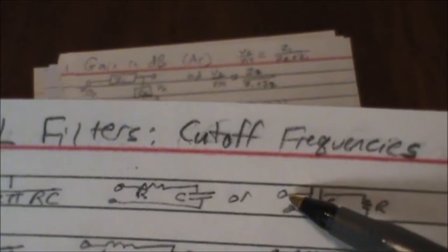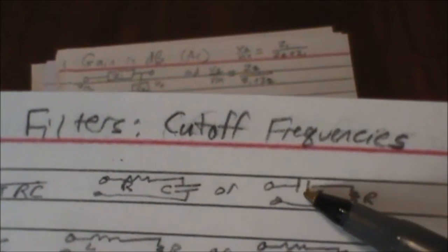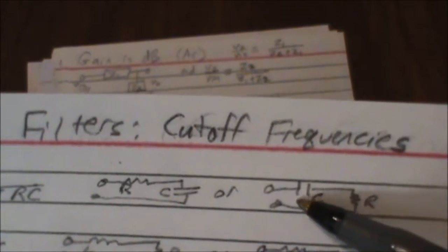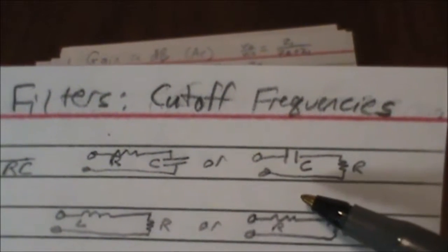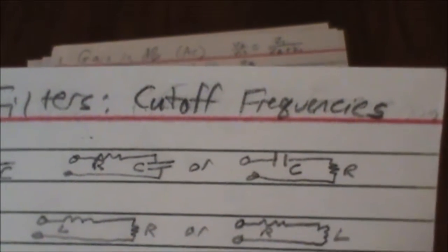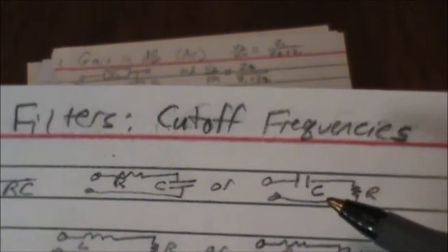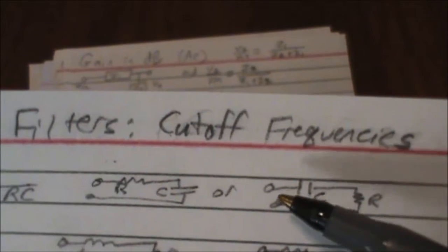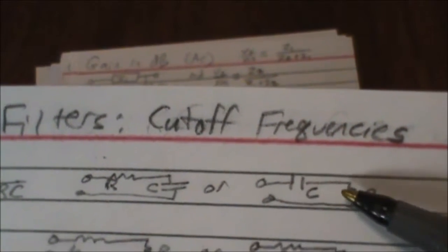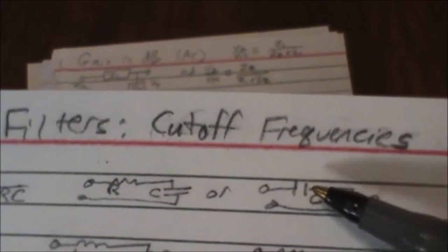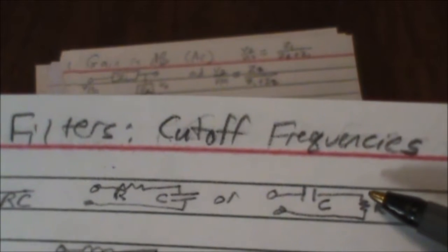But then at a low frequency, it's going to hit this capacitor and say, hey, we're exceeding that 5 tau value. If you remember the 5 tau for how much time it takes for a capacitor to charge and discharge, if you have a really low frequency, lower than our 5 tau, then okay, it's going to block current flow from getting through here.